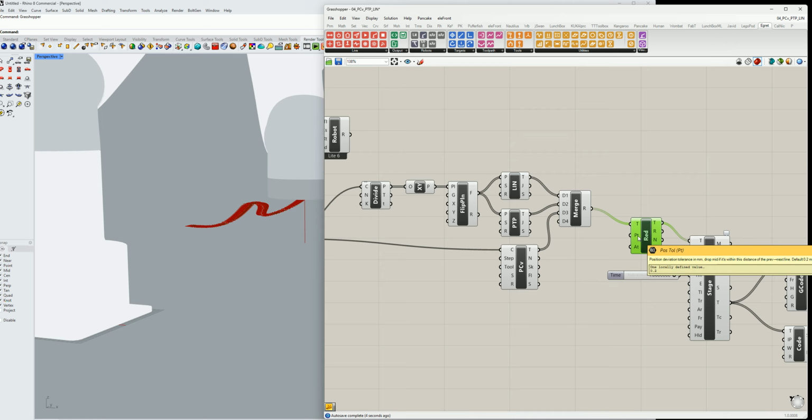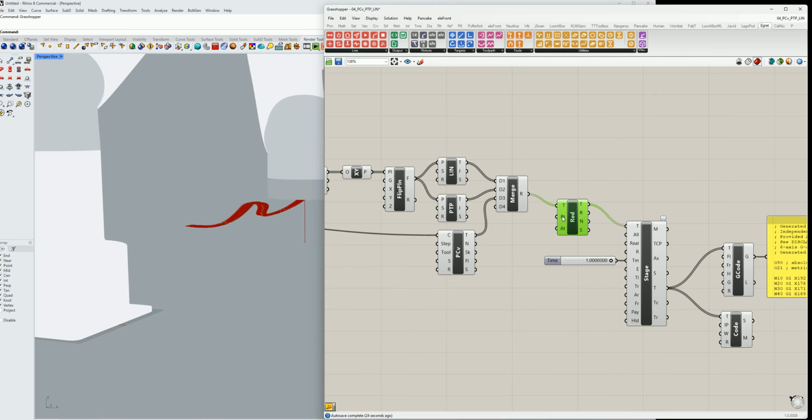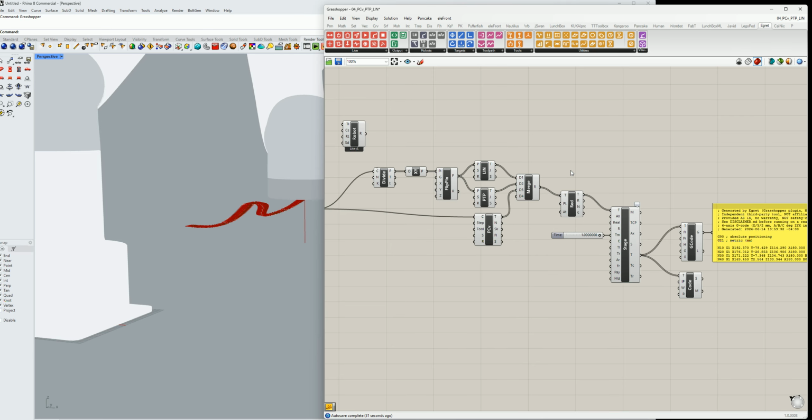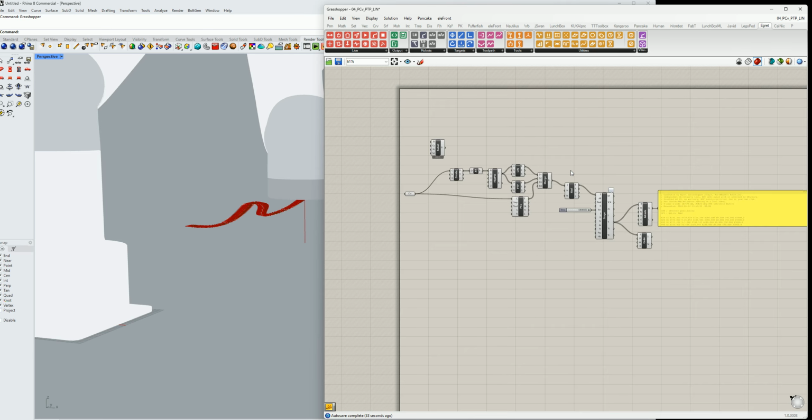curve. Sure, there's going to be some deviation. You can see I have a 0.2 millimeter deviation in the path, but I dropped the toolpath by 200 points. Or I dropped it to 1/3 of what it was. So, you can play that up. If I cranked up this tolerance, it would start increasing more and more points. And it would play out that way.